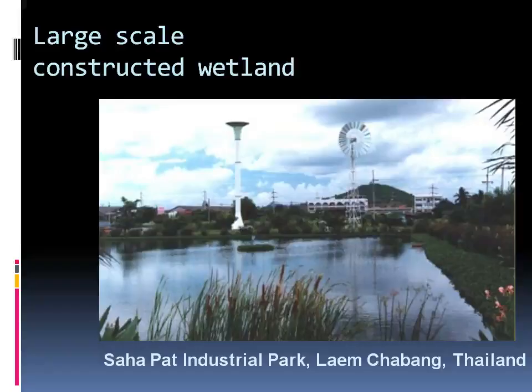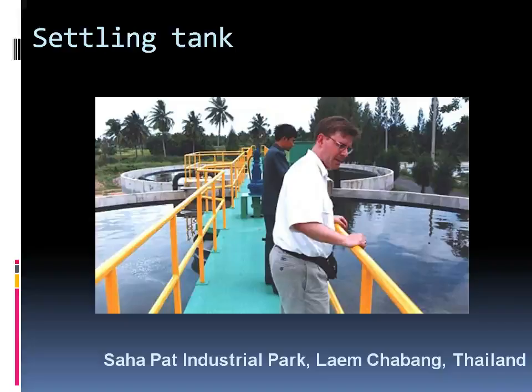Then the activated sludge process step. In this step, the sewage is pumped into a huge tank where it is mixed with air bubbles and bacteria-rich sludge for several hours. The organic matter is consumed by bacteria and the mixture is pumped out to a sedimentation tank, allowing the sludge to settle out for reuse.